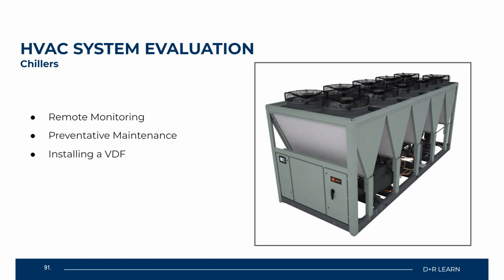You do want to run logs, make sure you're monitoring and writing down your logs, and your tubes and also your coils. You want to make sure those are clean and those coils are able to have a great heat carryover or exchange during operation.